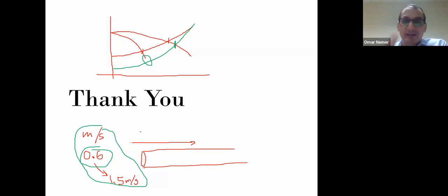And the second thing, we need to see the intersect between the system curve and the single pump curve or the two pumps curve. We have to make sure that there is an intersect between the curves, like we see here, here and here. If we satisfy these two conditions, we are okay, whether you use one pump or two pumps together.